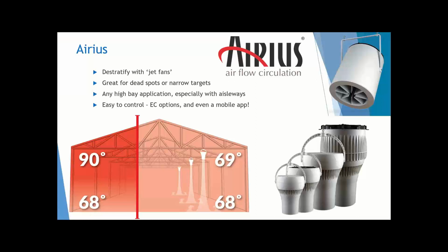So let's talk about jet fans. Aire is a company that we've partnered with to provide jet fans. They're actually the ones that really pioneered this technology. They're really good for dead spots and narrow targets. Instead of high volume, low speed, they're sending a column of air down where it hits the floor at about 150 feet per minute, and it will circulate that air and destratify it that way. So this is really great, like I said, for narrow targets. Anytime you have aisleways, this is a really good application to use.